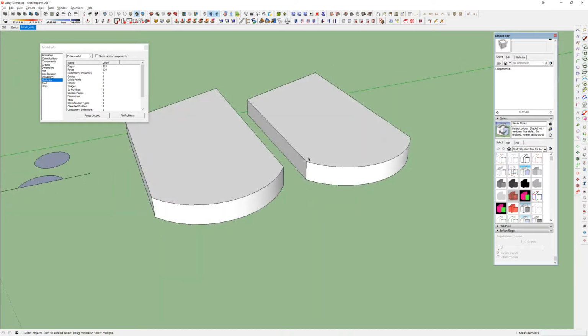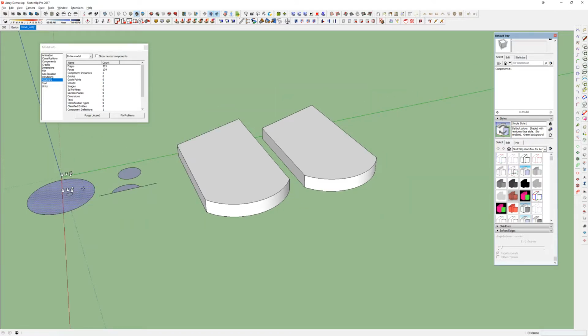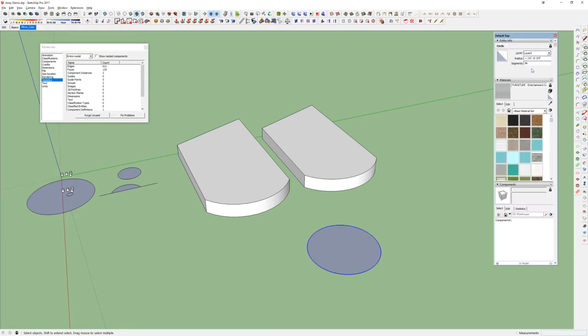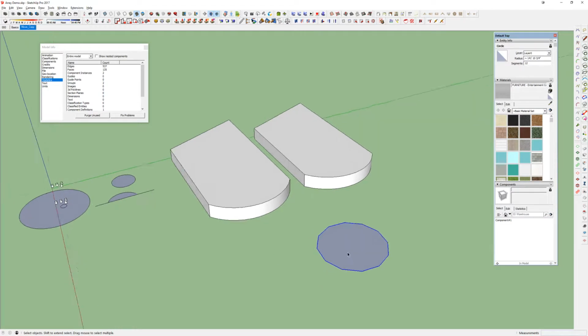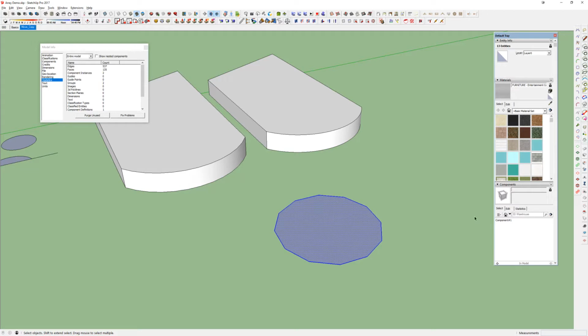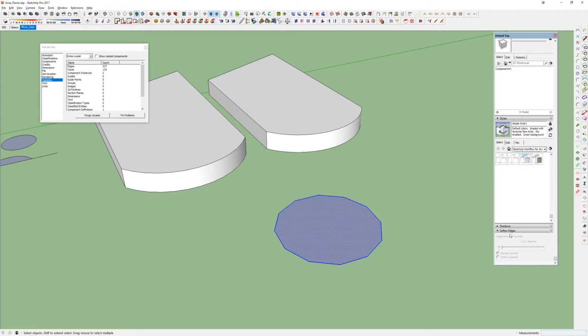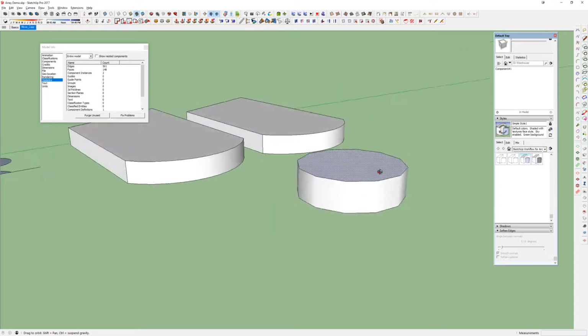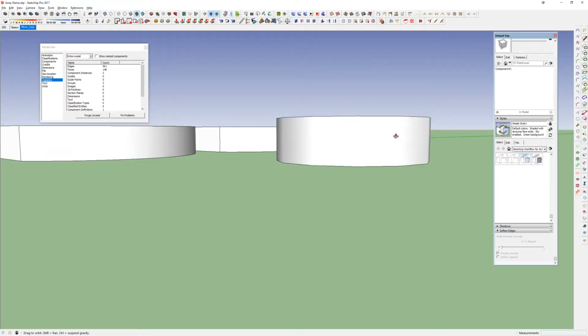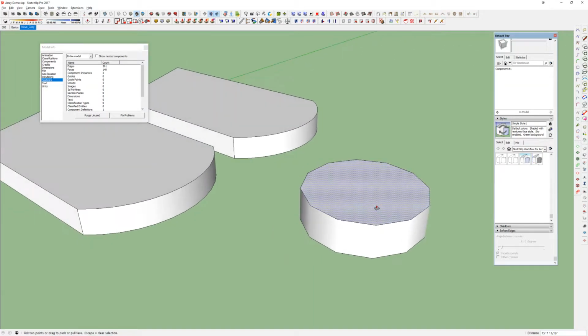So you can see that softening affects the look of your 3D objects, but not your 2D faces. If I take this circle, for example, which is set to 96, I'm going to knock it back down to 12. If I hit Shift S for my softening, you can see that this whole thing right here is grayed out because it has no effect on 2D shapes. And even pulling this up, looking at it from this perspective, it smooths it out very nicely. But anytime you start getting any kind of three-dimensional look to it, you can really see how rough this looks at this scale.